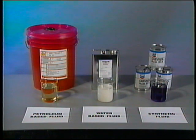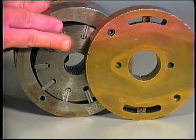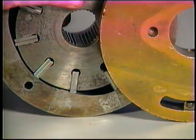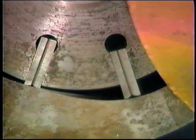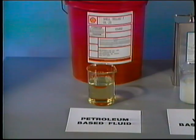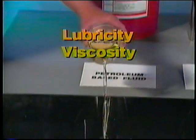In addition to transmitting hydraulic energy throughout the system, all three of these kinds of hydraulic fluids provide lubrication. That is, they reduce friction. Without proper lubrication, metal-to-metal contact, for example, between the vanes and the inner surface of this rotary pump, would cause the pump to heat up and wear out very fast. Fluids that lubricate systems properly will have two important characteristics: good lubricity and the correct viscosity.